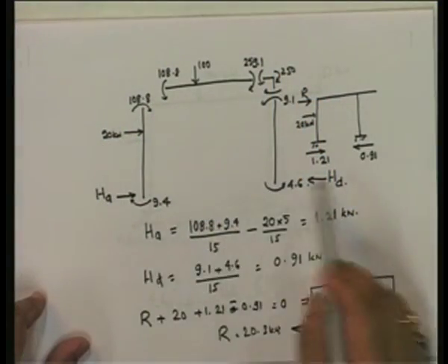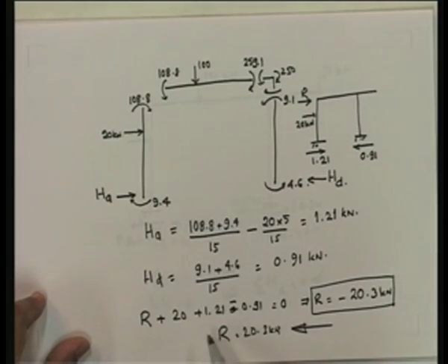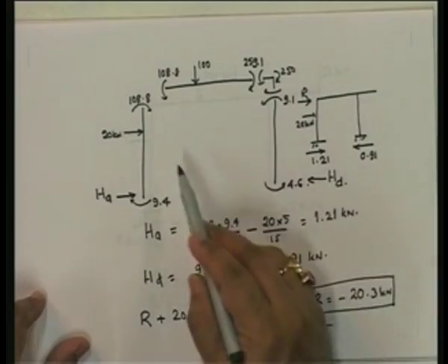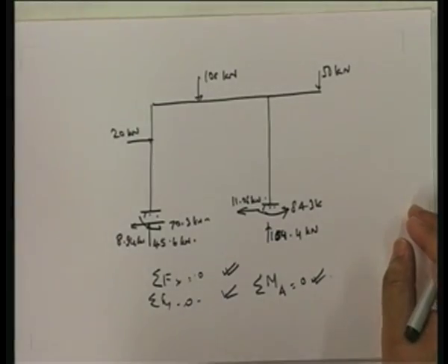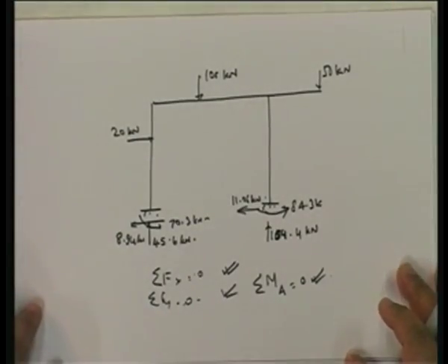Okay, so this in essence finally tells you that you have a situation in which you do have to solve a no sway moment distribution. By solving the no sway moment distribution, you get the no sway moments. From the no sway moments, you compute the horizontal reactions and you compute the total reaction required to ensure that there is no sway. Then the next step is to assume that there is sway and compute the load required to give you the sway that you get.